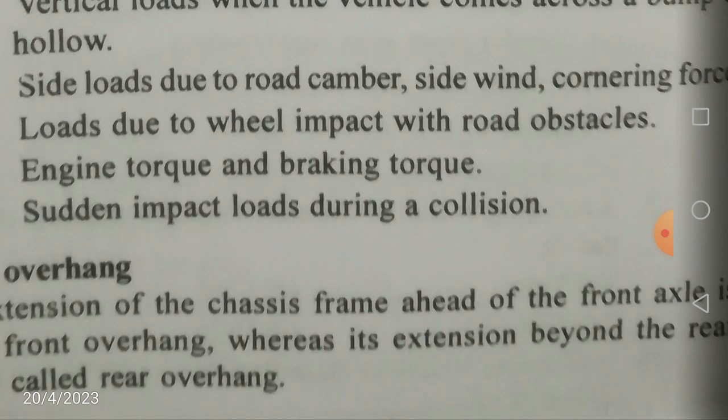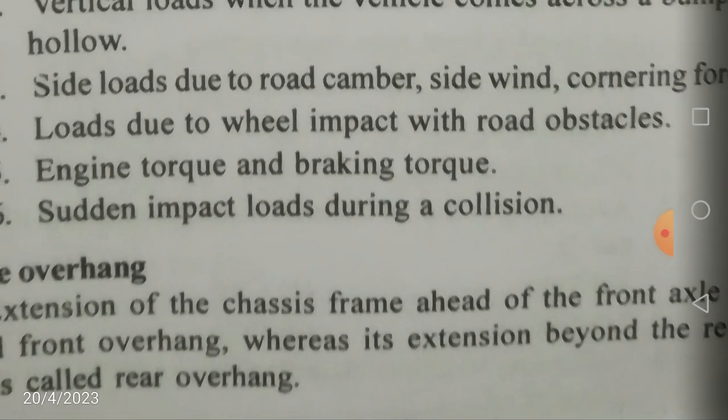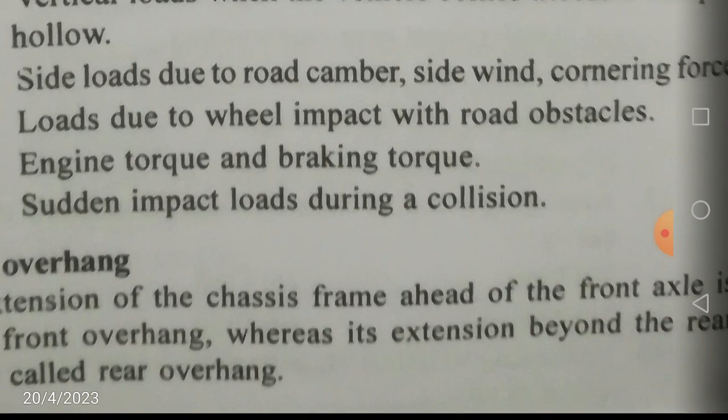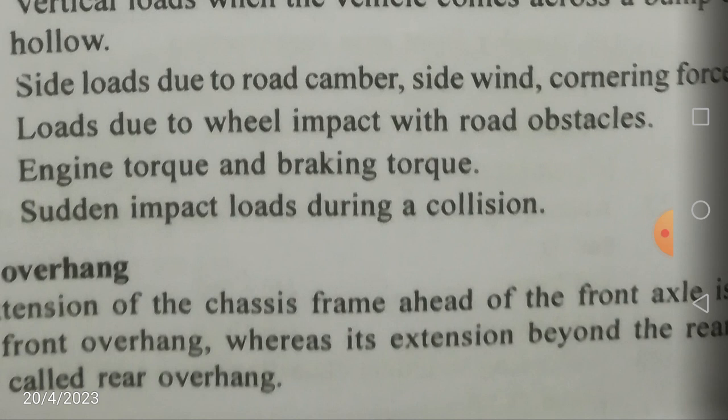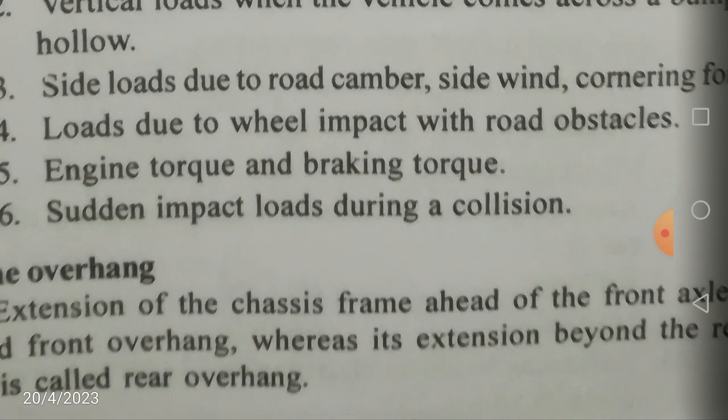We have manual transmission and also automatic transmission. In manual transmission, both the clutch and gearbox gears are operated manually by the driver, but in automatic transmission, both the clutch and the gears, first, second, third, are operated automatically by some mechanical system. In semi-automatic systems, your gearbox is operated automatically by mechanical members or some arrangement, but your clutch is still operated by your driver. So that's called semi-automatic transmission. So we have got three types of transmission: manual, semi-automatic, and automatic.